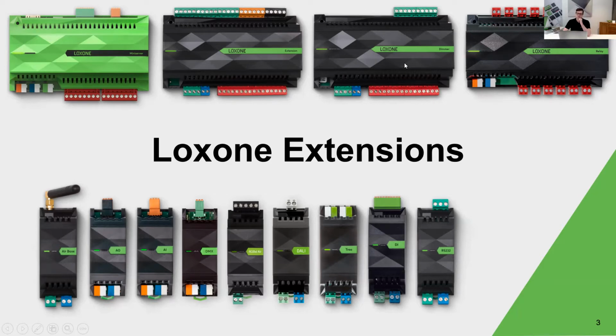With mains dimming, big thing to bear in mind is we are quite cool in the fact that we can do both leading and trailing edge, and you can actually change it on a by-channel basis. So this one could be leading edge and that one could be trailing edge. It's really cool. Not a lot of manufacturers can do that. We can also do both 0-point crossing of the voltage and the current for dimming as well, both on leading and trailing edge. So we can very nicely change between whether you're doing a traditional resistive load or a capacitive load like an LED.